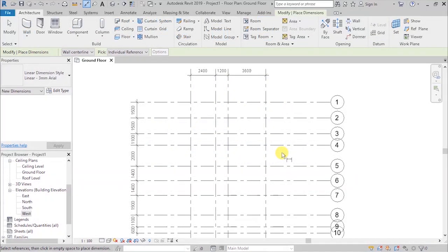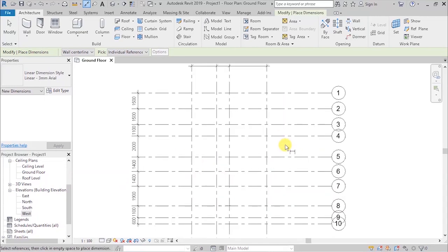So as we go on with our project, I'm just pointing out that just because you are seeing me use these construction grids, that does not mean that this is the only procedure that you have to follow when you're working in Revit. But for me, I find that these construction grids make it easy to place the load-bearing walls for my model, because what I'm planning to do is to have, at the intersection of these grids, my load-bearing, let's say, columns, and running through these grids will have my load-bearing walls.